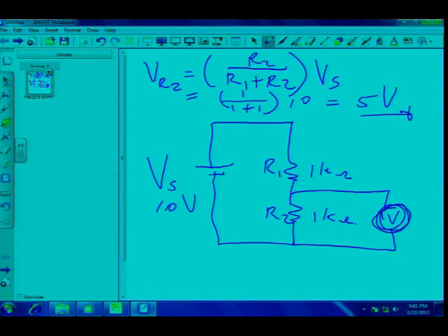Okay, let's say for instance it's low. Let's make the internal resistance of my voltmeter also equal to 1 kilo ohm, just to keep it simple. But anyway. What do I know if I have 2 resistors in parallel of the same value? What is the total resistance going to be? Same value, the resistance is going to be half, no? So 1 kilo ohm, I'm going to have a total resistance of 500 ohm.